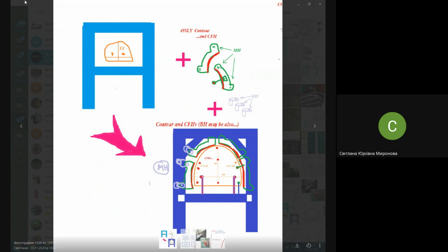In the template, we have what we have agreed: base holes or coordinate fixing holes. Either you use coordinate fixing holes which coincide with frame coordinate fixing holes, or you have very special ones, what we wrote as lilac things, like base holes on the horizontal constructing plane of the fuselage, which are not in use during the work of the jig at all.